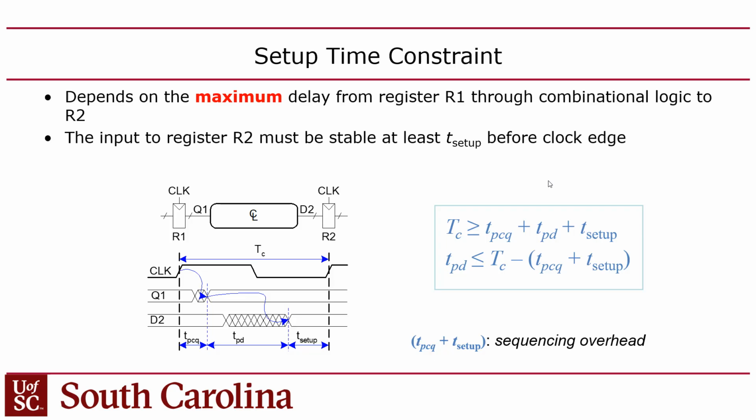Because you're not doing gate level design, you're doing HDL level design. So you only have an indirect control over that because the synthesizer is what's actually generating the gates, right? But of course, there is a relationship between the HDL and the propagation delay, as I mentioned in your CPU. If you're trying to do ALU and branch resolution in the same cycle, then that's probably asking for trouble, right? Because that's a lot of stuff.